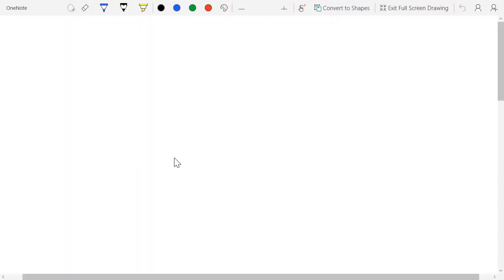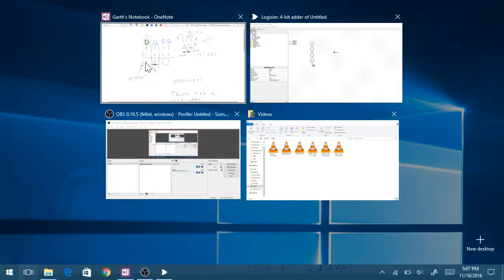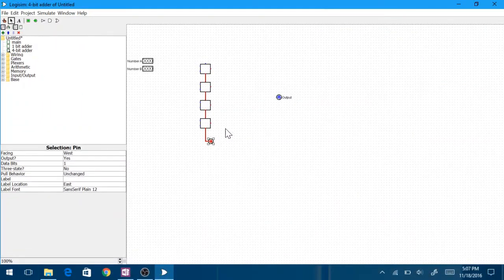If we look back at our expression, here's a 4-bit number, and I want to add it with another 4-bit number, and I get an answer, but these numbers were too large, and I happened to get a 5-bit answer, so I had some overflow bit here. This bit was turned on, indicating there was an overflow. Since that was the last bit coming out, the carry out for our last adder, this is our overflow bit.